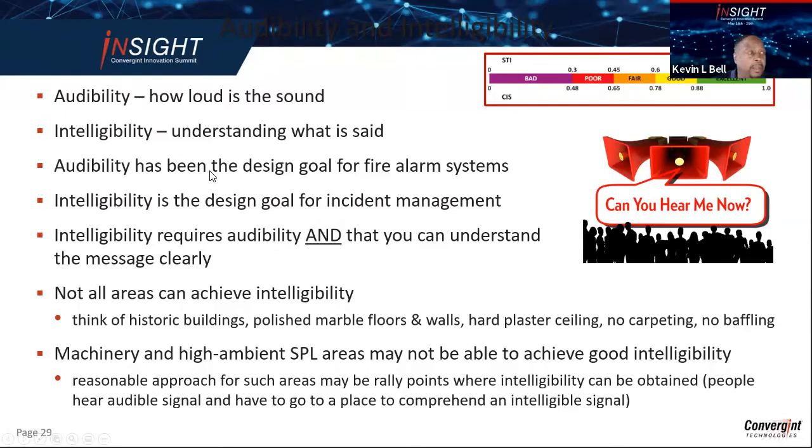Audibility is how loud the sound is, but intelligibility is what is said. With fire alarm systems, audibility, yes, you want it as loud as it can be, so we can tell people to evacuate. But with mass notification, we want intelligibility. We want to know what's going on and what we should do. So for incident management, intelligibility is most important.